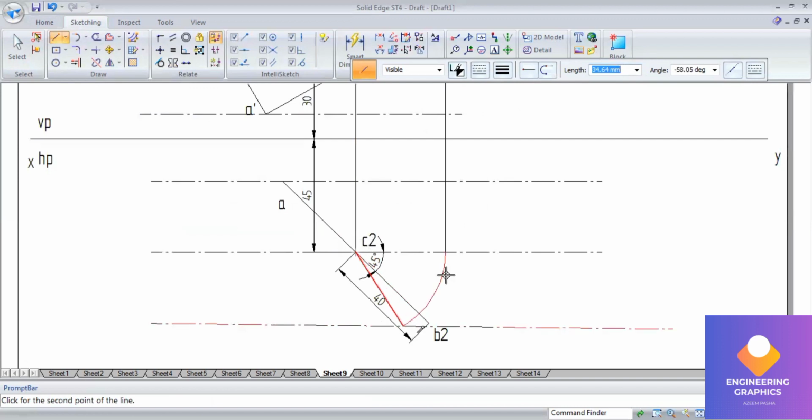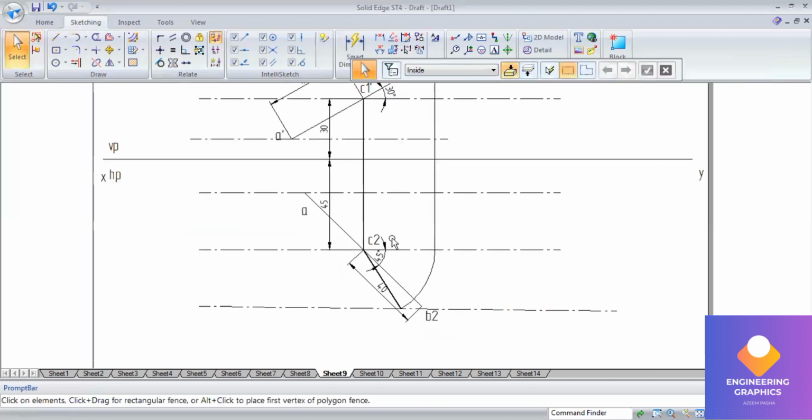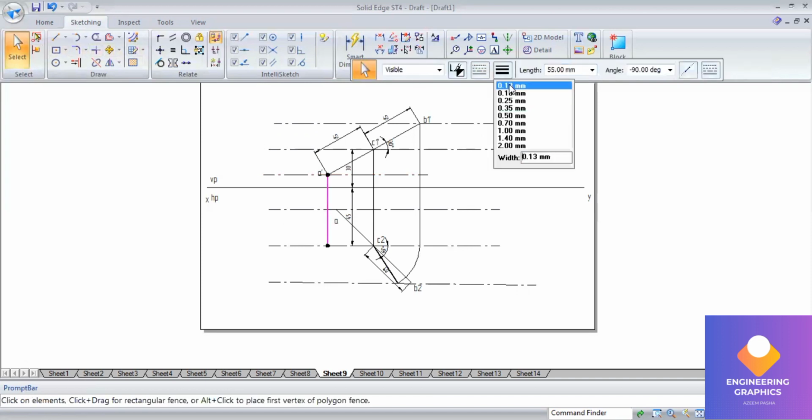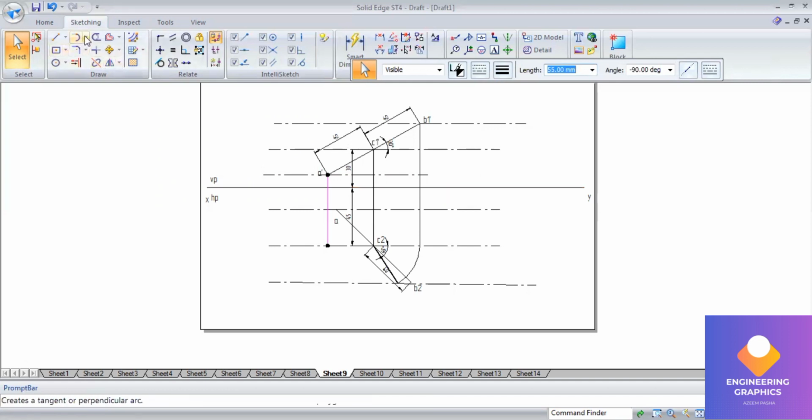Here also you can see that a dotted line appears. Just move the cursor over that point and drag it, and you'll get that dashed line. This is where you have to construct the locus line. Now using this true length, we should construct the upper end length.